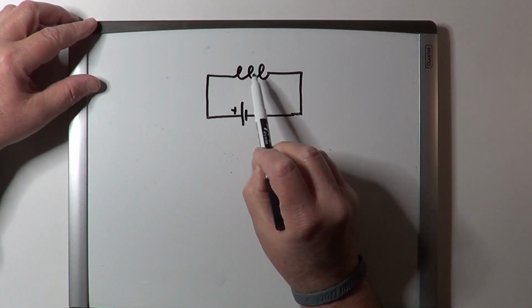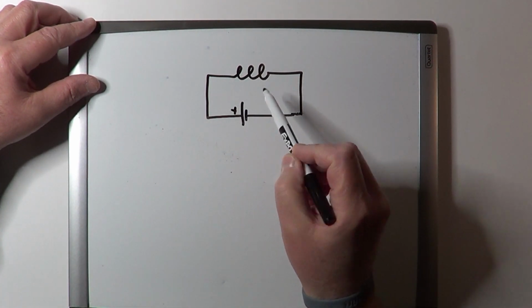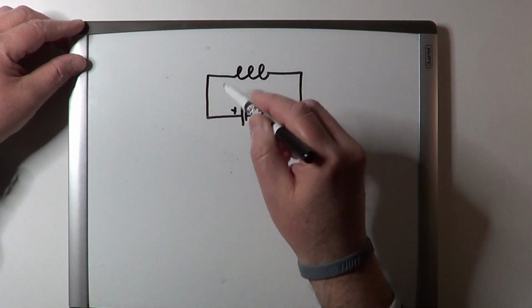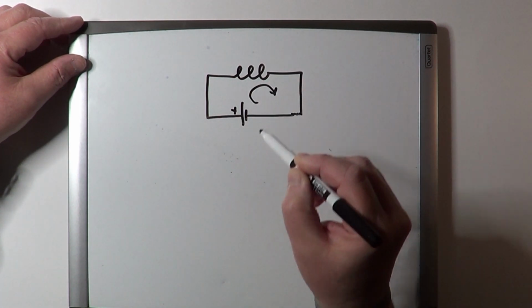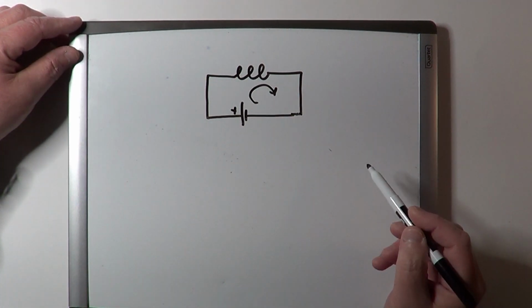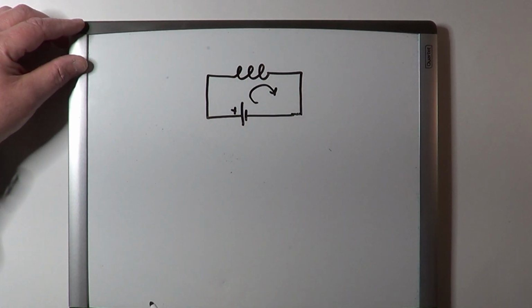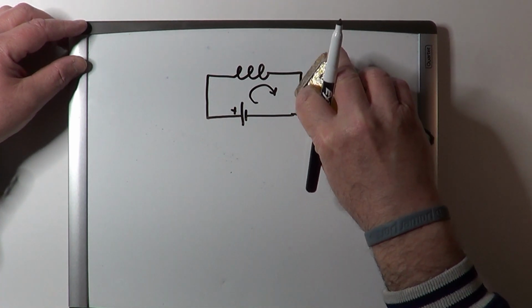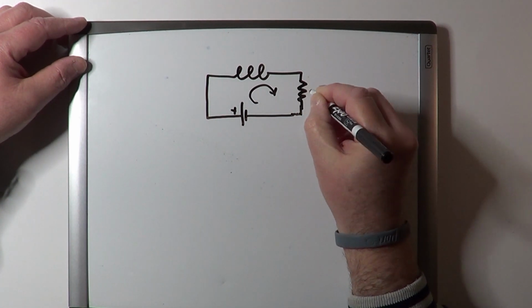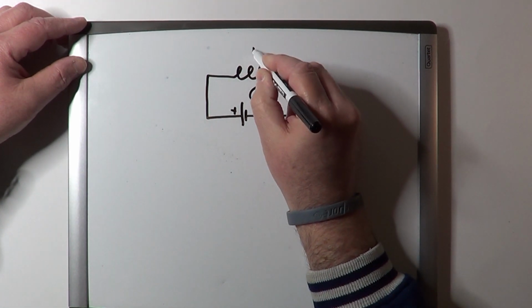Because the inductor is made usually of good conducting material, like copper for example, a considerable amount of current will flow through the inductor itself, causing eventually to burn the generator or the inductor if the wire is thin. So let's put a resistor in series to limit the amount of current that goes through the inductor to a reasonable value. And let's put it this way, in series with the inductor L.